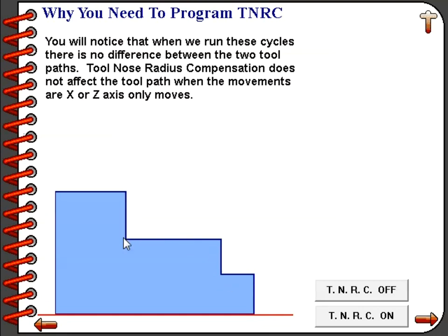In the previous two animations, when we machined the taper or chamfer, and when we machined the radius, both the x and the z-axes were cutting at exactly the same time. That is when tool nose radius compensation has to modify the tool path for us to accommodate for that difference between the theoretical sharp point and the actual radius on the tool.